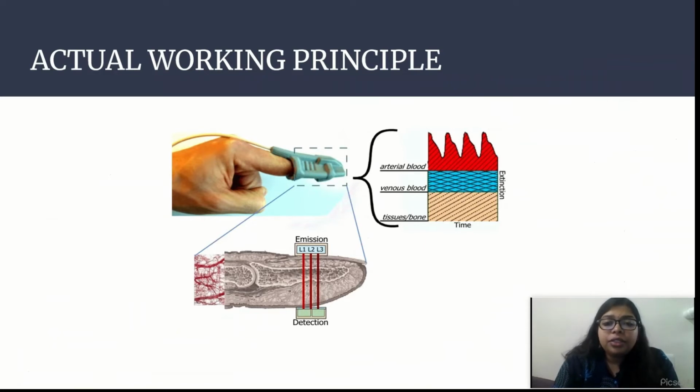The ratio of the red light measurement to the infrared light measurement is then calculated by the processor, which represents the ratio of the oxygenated hemoglobin to the deoxygenated hemoglobin, and this ratio is then converted to SpO2 by the processor via a lookup table based on the Beer-Lambert law. The signal separation also serves other purposes. A plethysmograph waveform representing the pulsatile signal is usually displayed for a visual indication of the pulses as well as signal quality, and a numeric ratio between the pulsatile and the baseline absorbance can be used to evaluate perfusion.